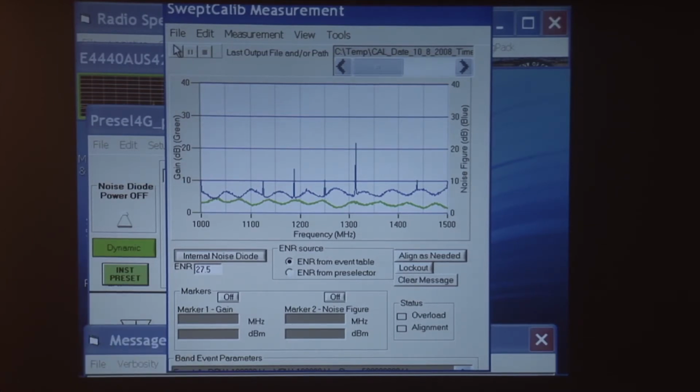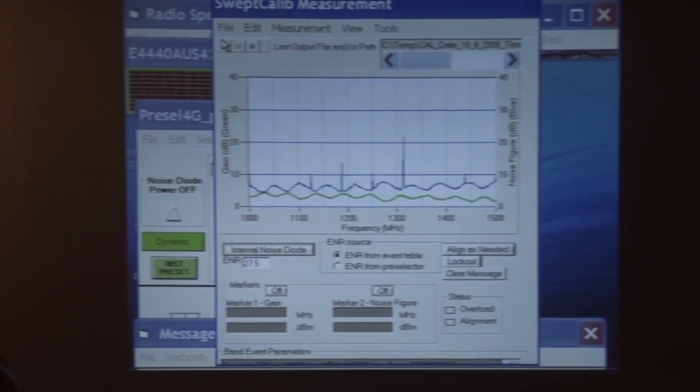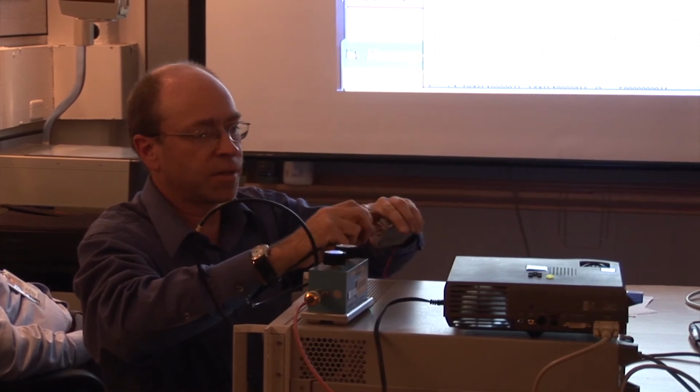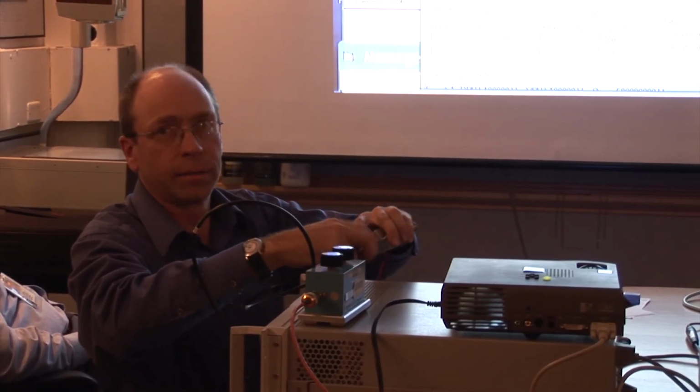All right, so we'll bring the RF line in. Bear with me for a moment while we do this. You can't see this on camera, but we have the RF attenuator feeding into a little auxiliary preamplifier. Let me make sure I get the right end here. Frank, what are those controls on the top of the unit there? The controls on top of the attenuator are the attenuator settings. I see. I can step it in 10 dB steps and 1 dB steps, and we'll see the use of that.